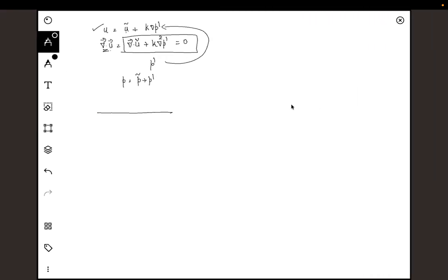Let's say this is my boundary cell, P, and it is exposed to ambient with heat transfer coefficient H, and let's say T0 is the reference temperature, and this is my last but one cell, Ti. The idea here is that the heat transfer should be balanced. If I apply a heat balance here, the heat that is going out is minus K times del T del X. I can approximate del T del X with the first order difference here. So that will be Tb minus Ti by delta X, which should be equal to H into Tb minus T0. This term, let's call it H external, and this particular term here, we can call H internal.